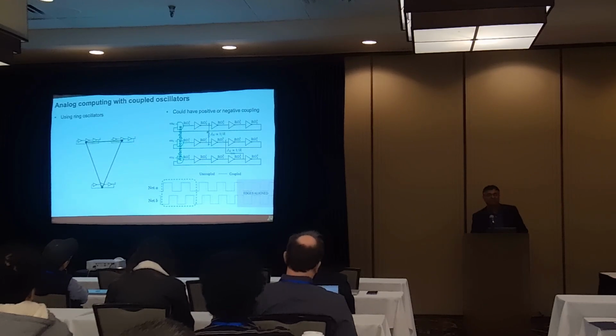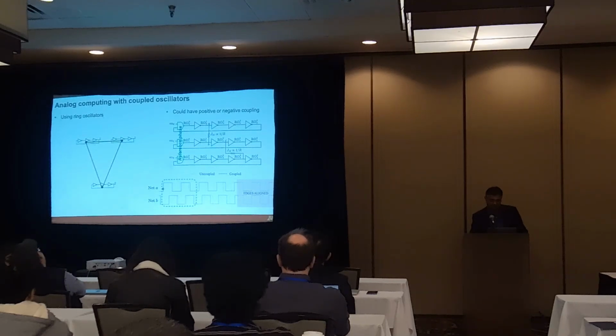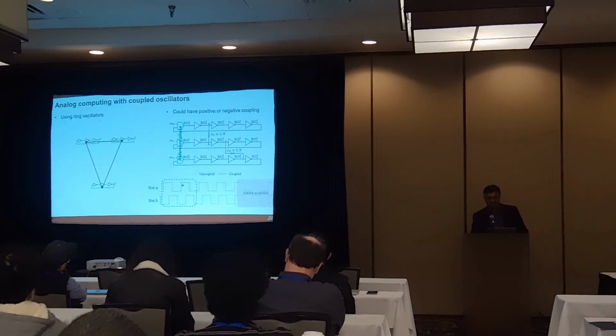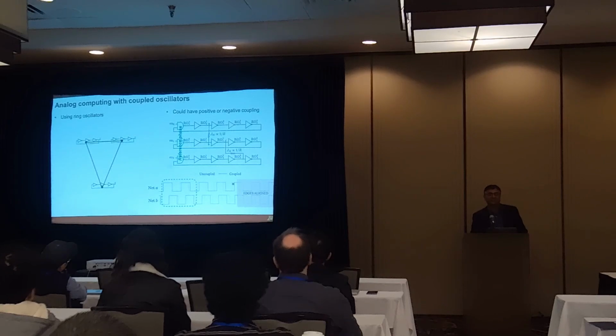So it's actually fighting that rise, which means it's going to slow down the transition. So instead of making the transition at this dotted line, it's just a little to the right over here. When it comes over here, A is trying to fall, but B is high. So as it's trying to fall, it's being opposed by this, so it moves a little to the right. Again, it moves a little to the right on the next phase, etc. And progressively, this moves to the right a little. The phase actually gets delayed.